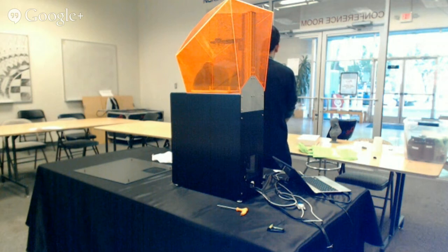To me, it makes sense that what I'm going to try to do is print two that are vertical like that and connect them. Yeah, because then you get the good surface quality of both. Because when we build like this, everything gets ugly because it's at an angle. Yeah, the angle is a difficult problem for flat surfaces.